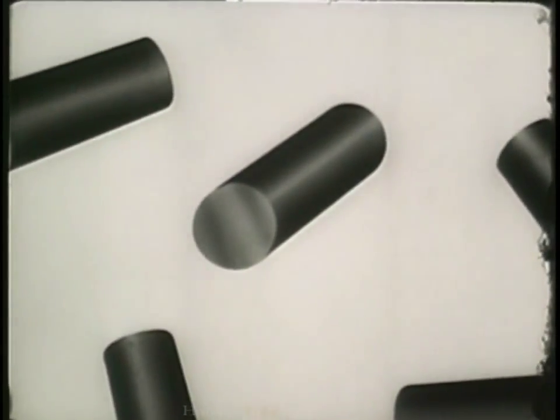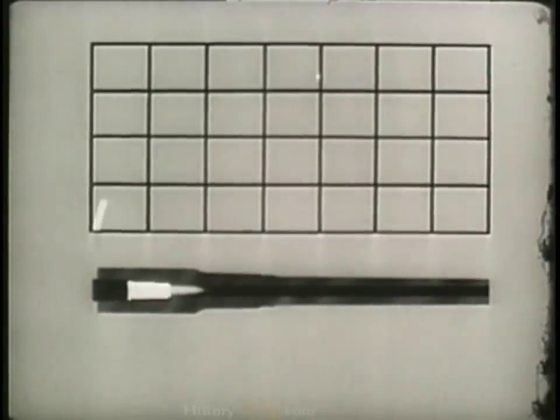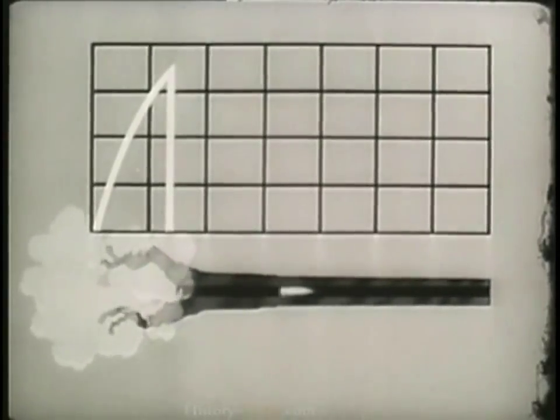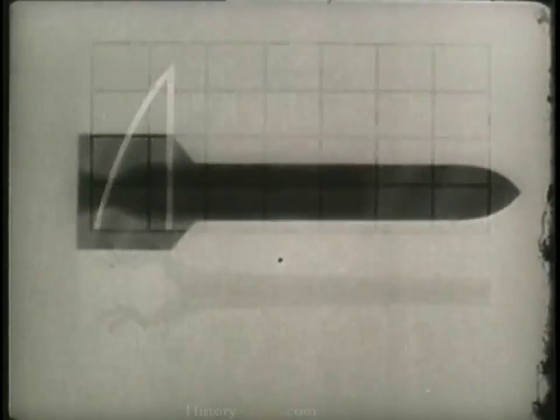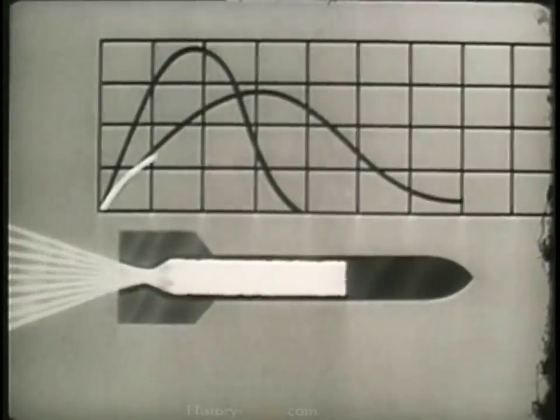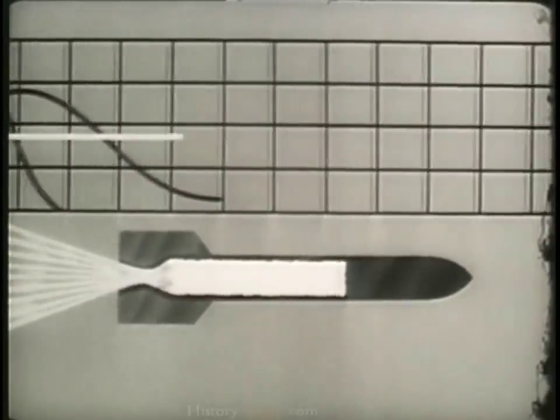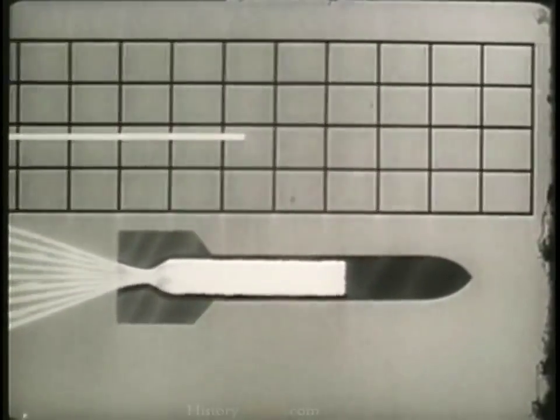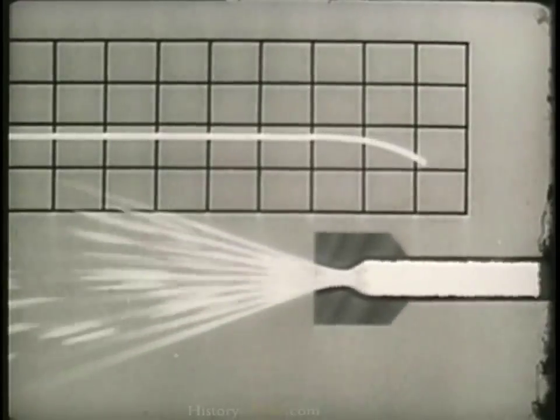But if we use digressive grains in a long-barreled gun, there's a chance that the higher maximum pressure produced will blow it up. For a rocket, we need a low, steady pressure, so we use a special neutral grain. The low pressure will not burst the lightweight rocket, yet gives smooth acceleration.